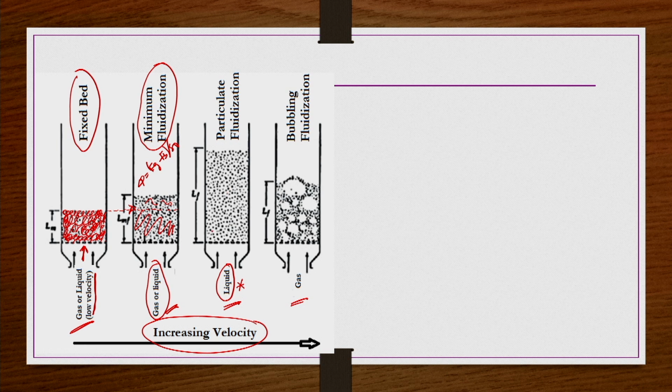And then you can see that at any location in the bed, you take the density of the bed, it is the same actually. That means at any location within the bed, if you calculate the volume fraction of the solids and the volume fraction of the liquid, it is not going to change much from one location to another. That is the reason this fluidization is so smooth.